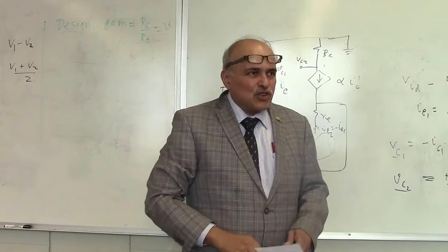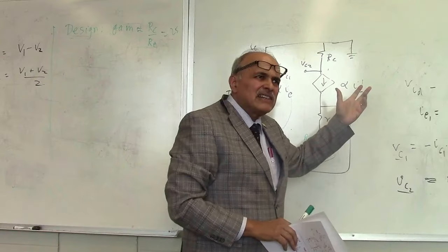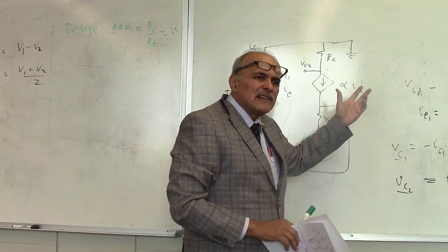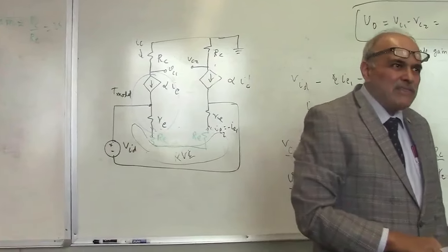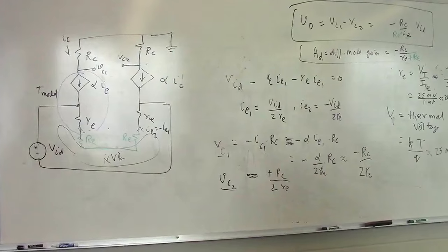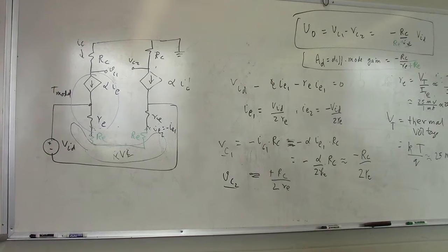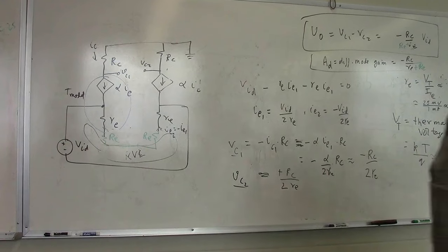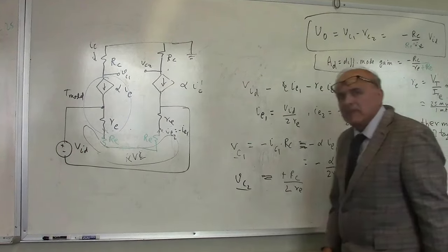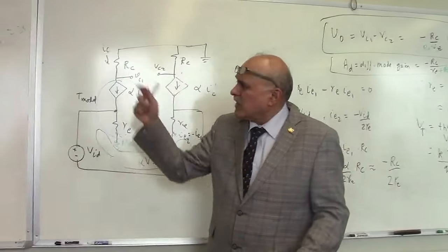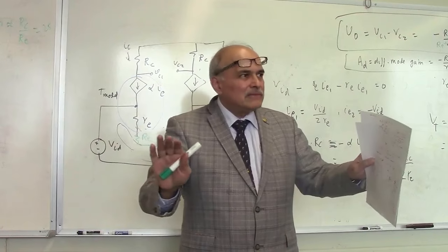Okay. So far so good. So you can now select the... that's the double sided, I think. Is it double sided or single sided? It's at 25. Anyway, you can figure it out. Single sided gain of 25? It doesn't say here, but, oh no, it says differential gain of 22 to 27, right? So you want the difference. Differential gain means that, because we said that this is the differential gain. So you want that number to be 27, so RC divided by RE should be 27. All right? So far so clear? This is more or less the problem.